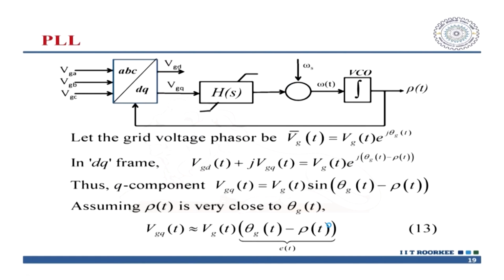Now, how do we do that? How will we calculate the theta? It is quite simple. What is the expression of your voltage? Voltage equals some constant 4.44 times flux density times A times N times F, and thereafter the winding constant, maybe Kw.